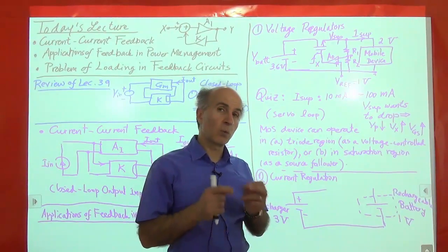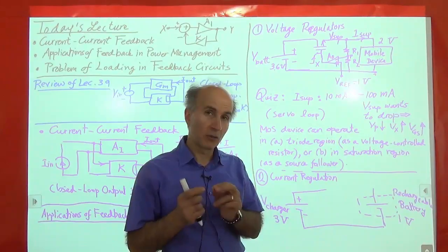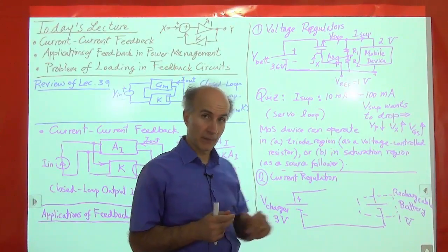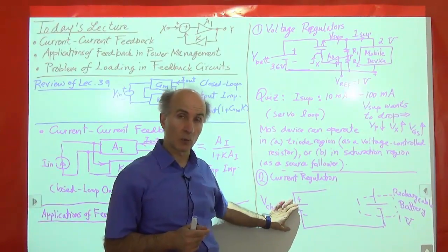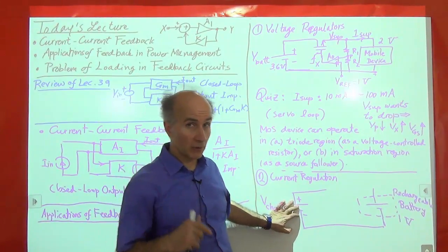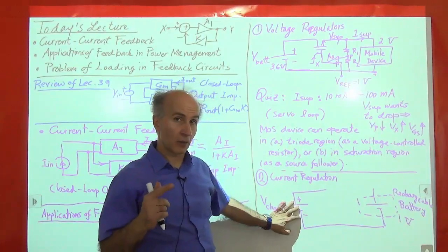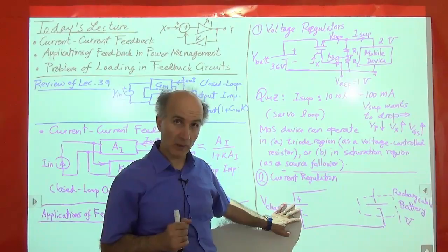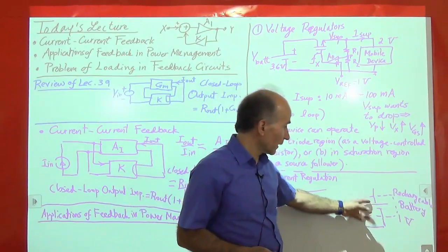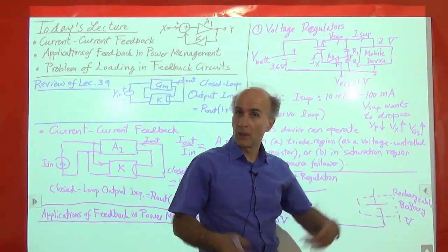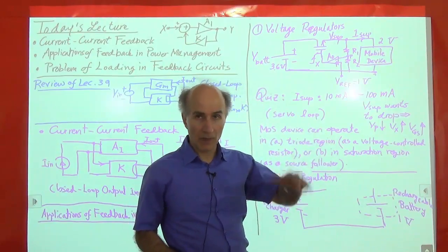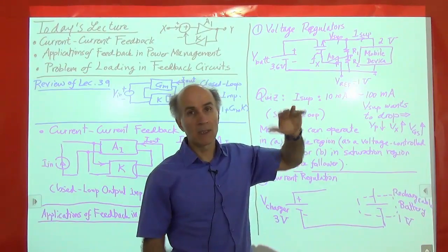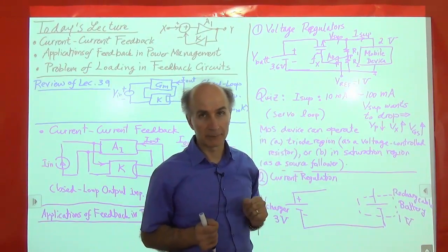So we don't want to charge a rechargeable battery with a constant voltage. Okay, this voltage here. We don't want to do that. What we would like to do is charge a rechargeable battery by a constant current. Okay, so it starts out, it has 1 volt on it, we start injecting some current, right? 20 milliamps, 50 milliamps, gradually just charging it up, right? Until the voltage reaches what we want, and at that point we stop.